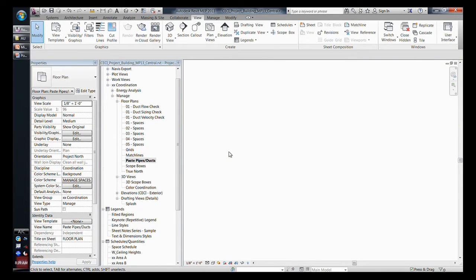You do that filtering across the pipe type parameters itself, PVC or steel or? Yes, it will. And I'm going to get to this, how I do my pipe types and duct types. And eventually, yes, it is crucial that you maintain them to be the same. You know, the pipe type here and the pipe type there, material-wise and everything, settings should be the same.